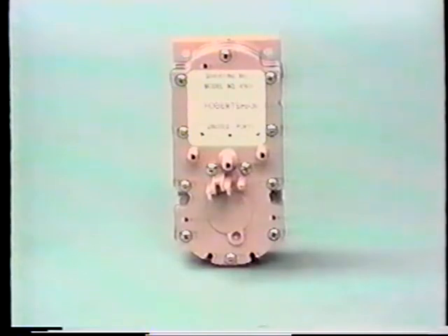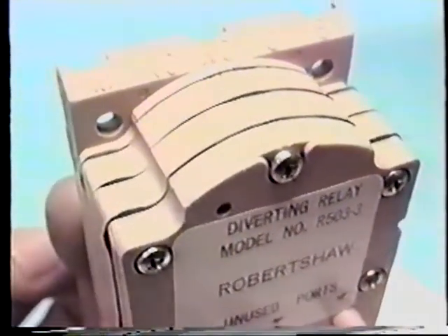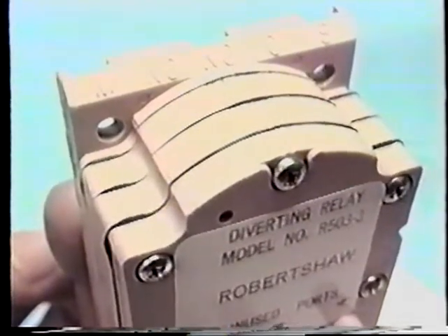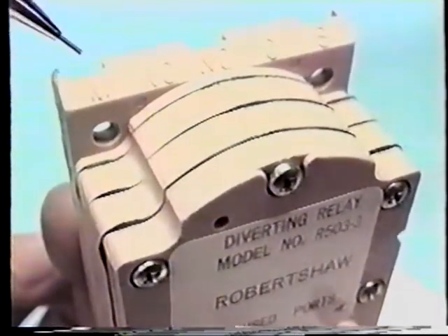This is the signal comparison diverting relay. This device is non-adjustable and has a single-pole double-throw snap-acting output. It is designed for use in systems where the comparison of two proportional input signals is required to divert or block a signal. For this device to function properly, it must have a main air supply of 15 to 25 PSIG piped to its M port.